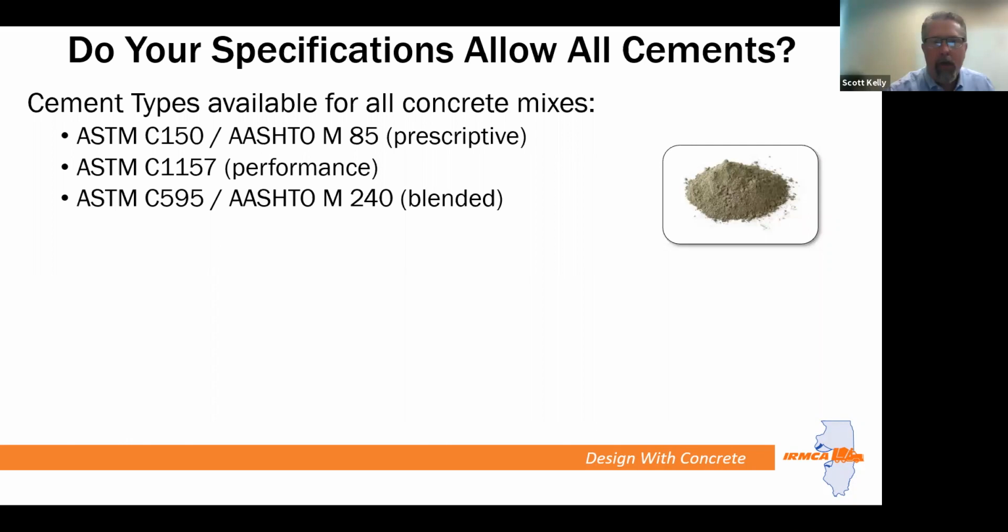Before we move into some discussion on cements and supplementary cementitious materials, the question is: does your spec allow all cements that are available, both in ACI 301 and also some of those new technologies emerging in the market? Some examples, and all three of these cements appear in ACI 301: ASTM C150, which is prescriptive in nature.